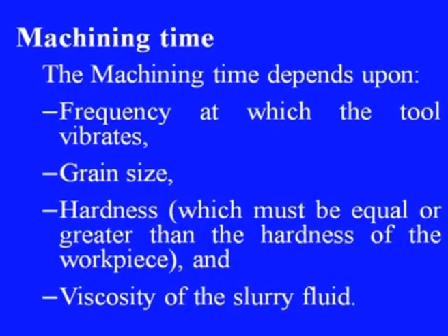As far as machining time is concerned, it depends on the frequency at which the tool vibrates, then on the grain size. We have already discussed the importance of grain size as far as MRR and surface finish are concerned. Then of course the hardness, which must be equal to or greater than the hardness of the workpiece, and then the viscosity of the slurry fluid.